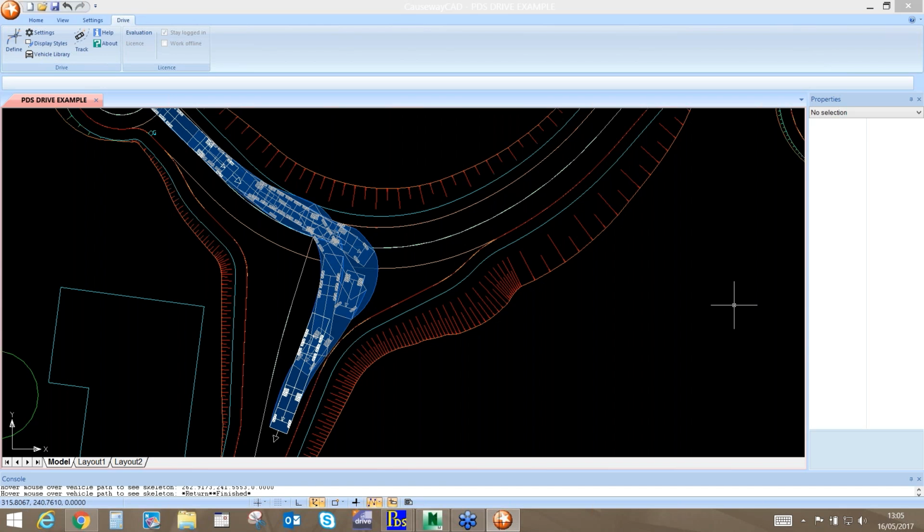Another question from Robert. How does Flow deal with model instability between storage and flow controls separated by short pipes? Does this require storage and flow controls to sit on the same manhole, similar to MicroDrainage? Very good question. We use the SWMM engine, which solves the 1D Saint-Venant equation. You're not having to put in dummy pipes, and you're not having the damping that you would get in MicroDrainage.